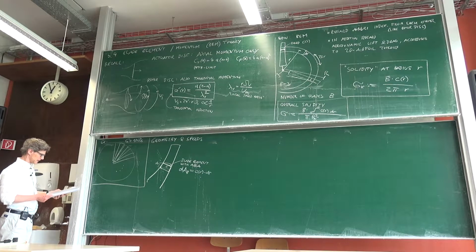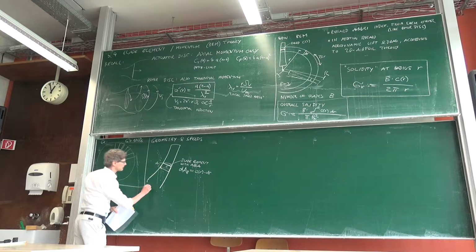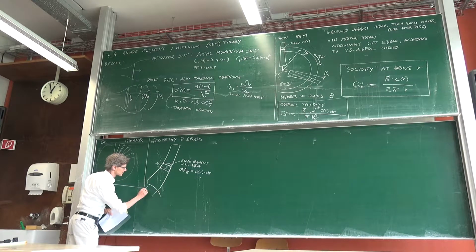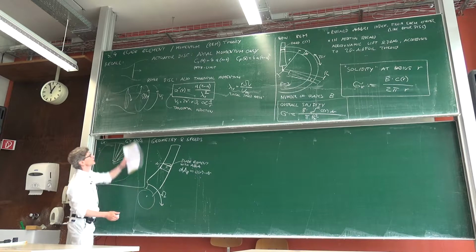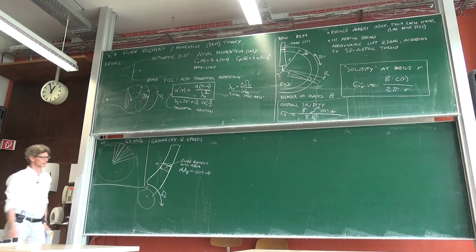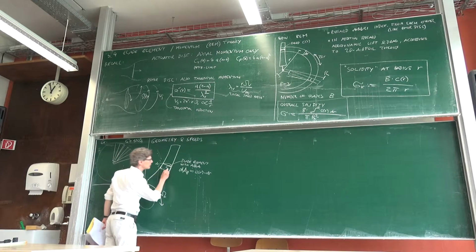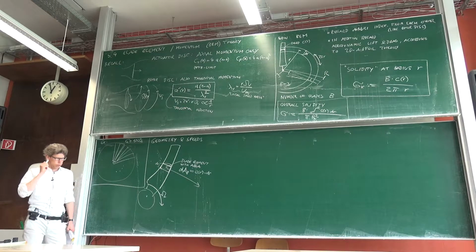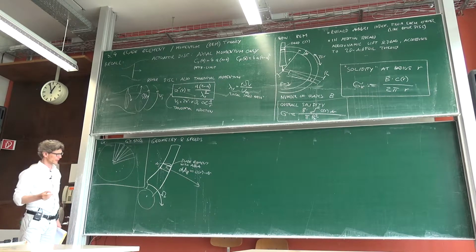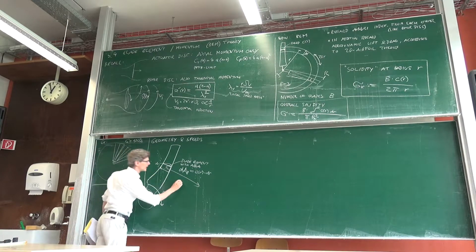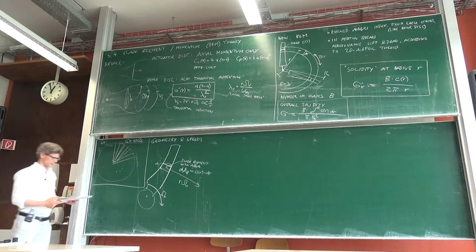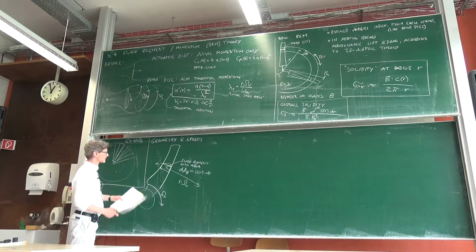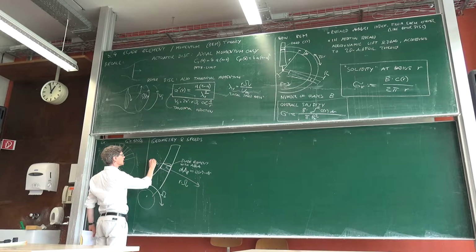Okay, so this is the blade element, and then let's look at what speed it has. The whole wind turbine will move. This is the hub, right? And there is a rotation speed, and the rotation speed is omega. We used that same omega before, so the rotation speed of our wind turbine is omega. So our blade element itself will move with a certain speed. It will move with a speed of r times omega, typically faster than the wind. Yeah? And then, in addition to this, there will be induced wind in this direction. Induced tangential wind.